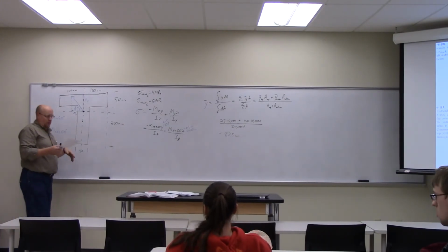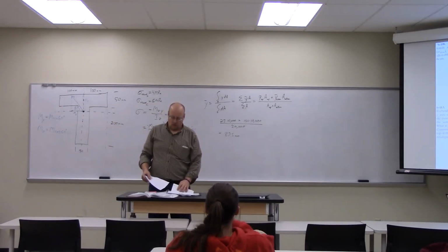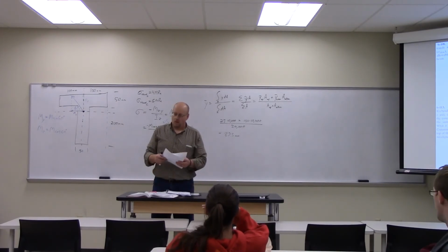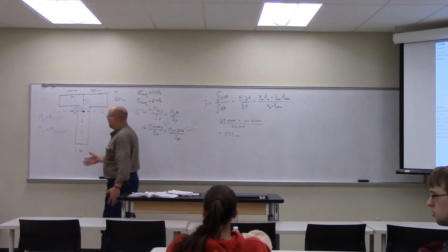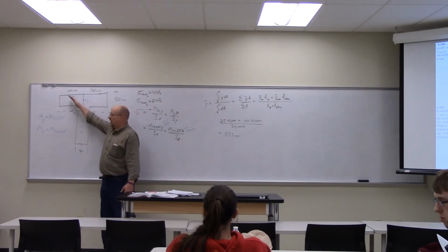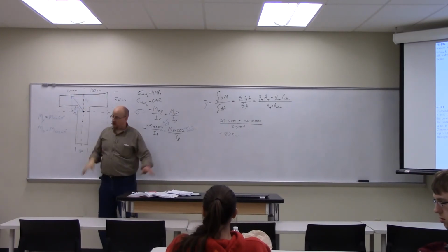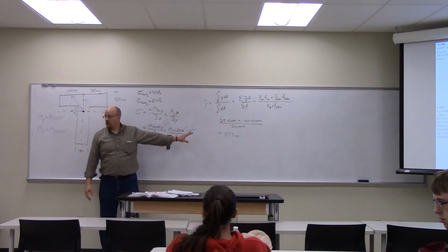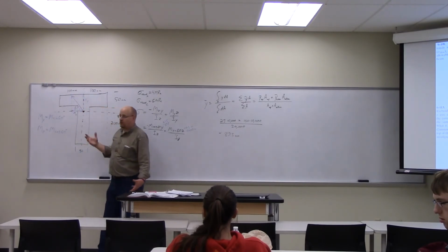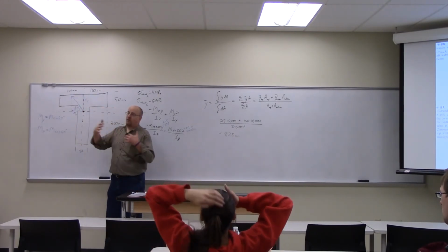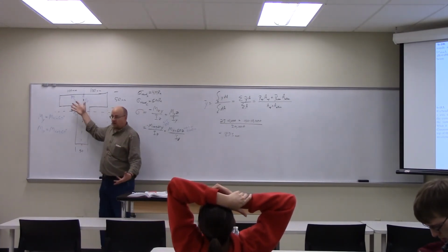Part of that is also knowing the neutral axis. We'd have to really know the neutral axis to find out for sure what direction it's going to rotate, because it's the position relative to the neutral axis that matters. So we don't necessarily know that the neutral axis is along this line. If we really wanted to find it quantitatively, we'd have to go in and find the neutral axis, tangent alpha equals tangent theta p, the ratio of the moments of inertia, find out where that neutral axis is, and then find out which point is furthest from the neutral axis. Because you always know the point furthest from the neutral axis is the one that's going to have the greatest stress. Okay? So you can go in and do that quantitatively.